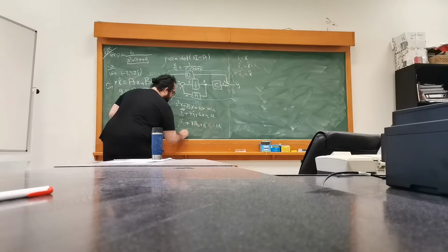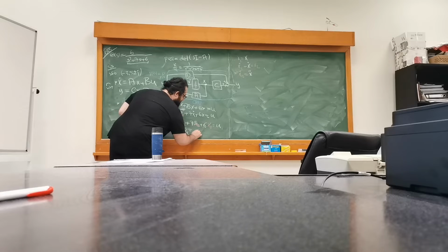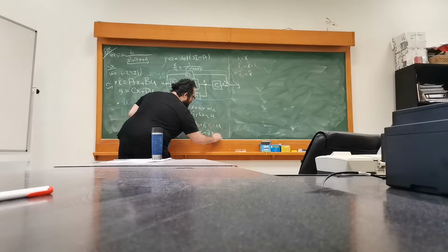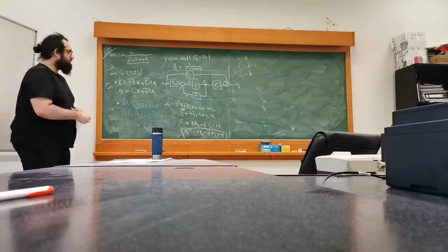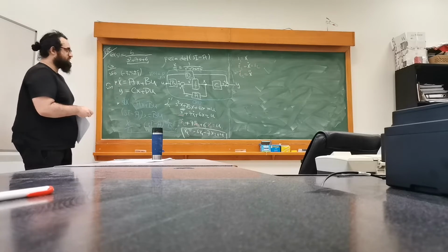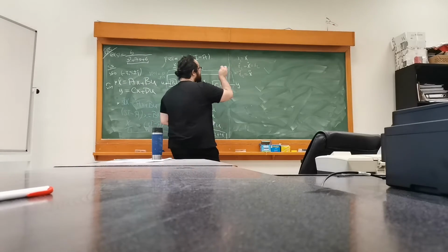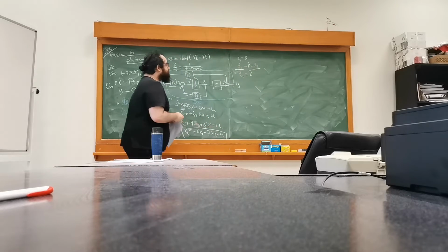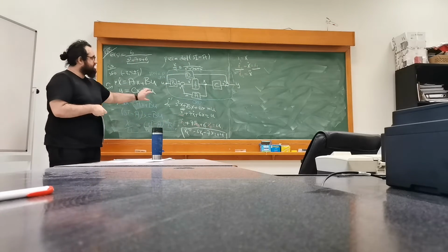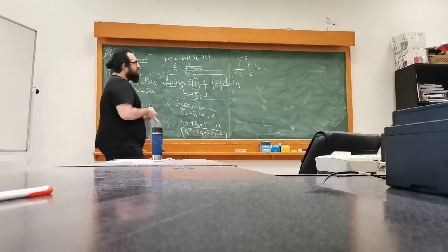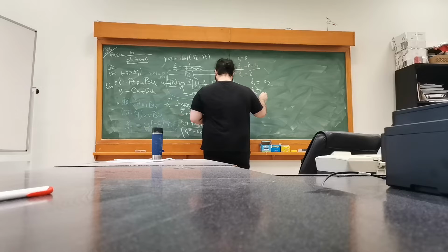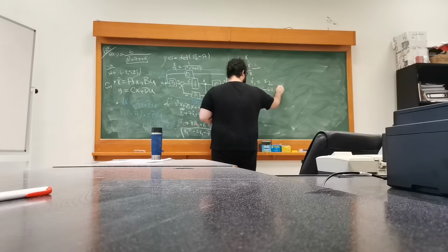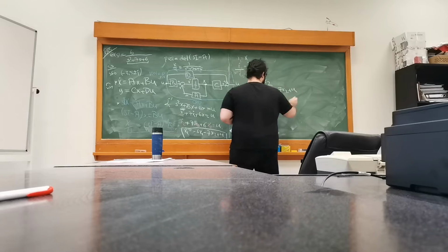Of course, I can work it out. x2 dot is now minus 6x1 minus 7x2 plus u. So this is the important relation that I want to work on, because this has almost the structure that I need. And I also have this x1 dot equals x2. I can use these two equations in order to define this second order differential equation, and it will look like this. x1 dot is x2. x2 dot is equal to minus 6x1 minus 7x2 plus u.